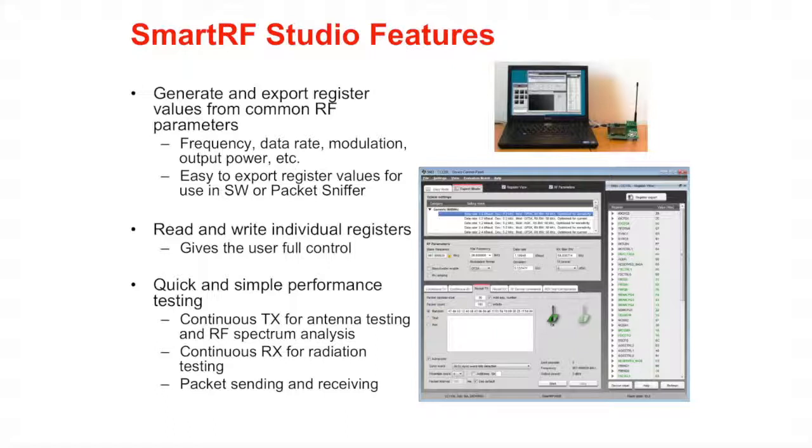In Easy mode, the user can easily get started by using predefined register values and radio configurations. In Expert mode, the user can fine-tune all settings and is given more flexibility when configuring how the device should operate. All of the device configuration and register settings are stored in XML files, making it possible to add custom configuration settings and to parse and reuse the files by external tools.